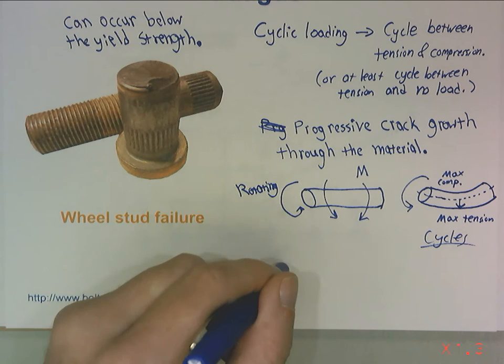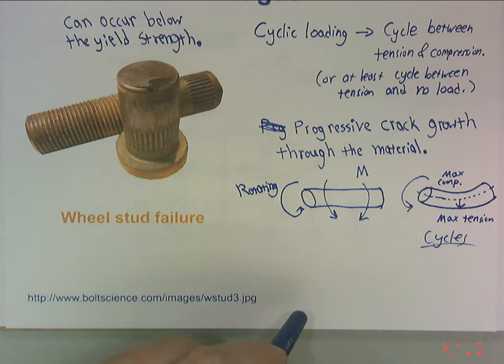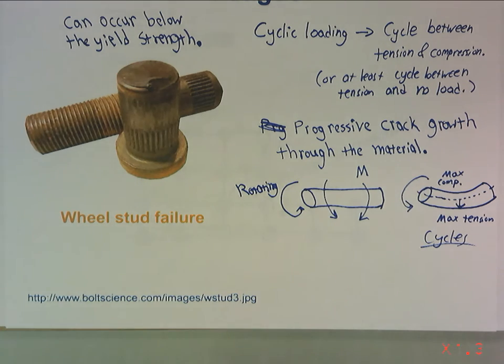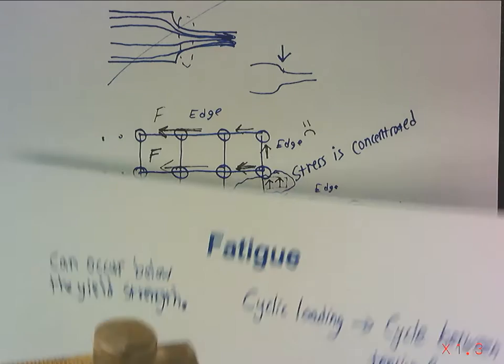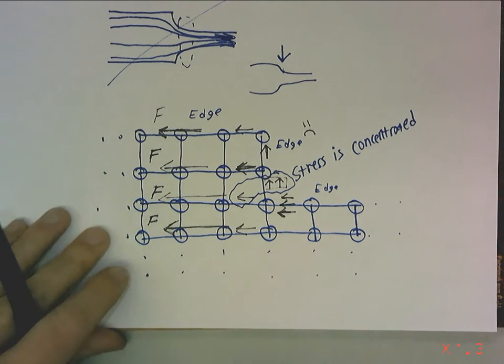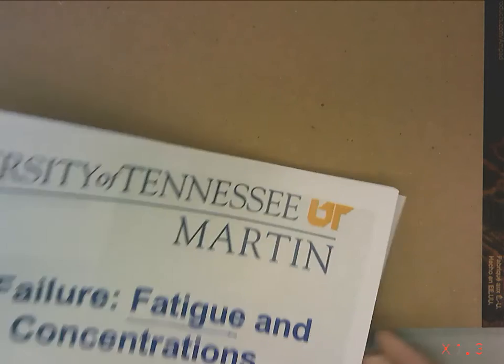We're adding an impact on top of our stress concentration every time that shaft spins around from being compression to tension. So there's a complex set of stress going on here. And that is what's going to make our fatigue crack grow.